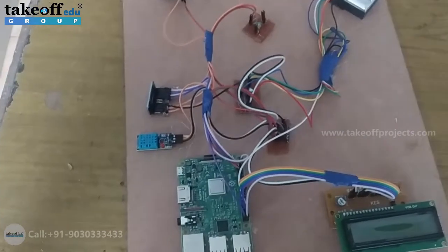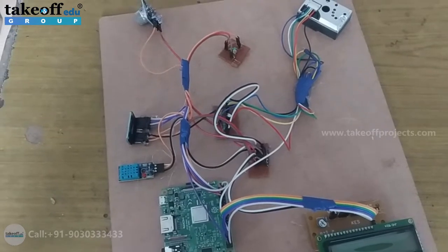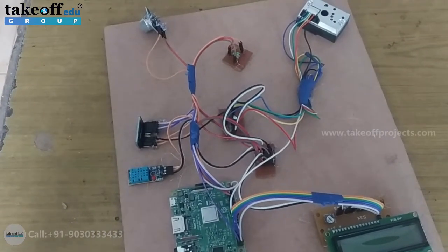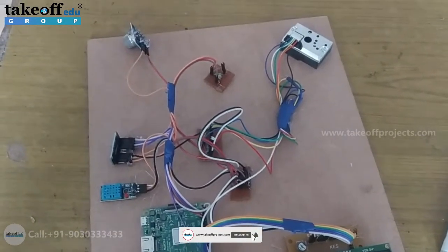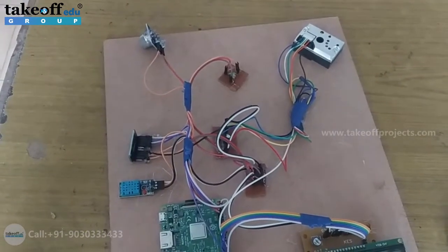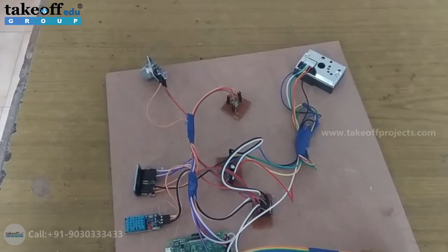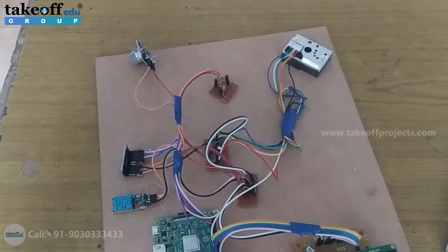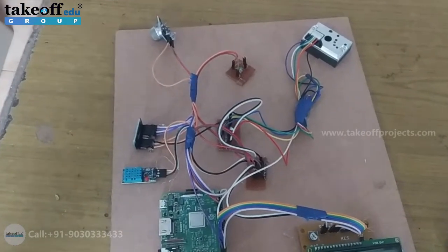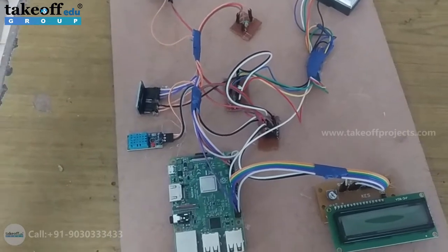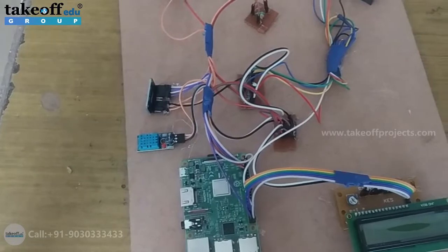So in the first step, we need to connect our Raspberry Pi to the laptop. For that, you need to change your mobile hotspot credentials to username project1, all small letters, and password 1234567889. Then you need to connect the same hotspot credentials to your laptop and install 2 softwares on it. One is Advanced IP Scanner, another one is VNC Viewer. So power on the Raspberry Pi using the adapter, and after a few seconds you will see the Raspberry Pi getting connected to your mobile hotspot.